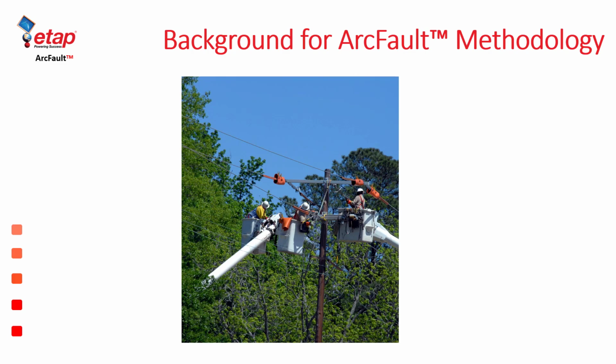Once the electrical workers cross these boundaries, they are exposed to a variety of potential arc faults. In overhead transmission systems, these arc faults may include series on-load arc faults, which occur as disconnecting equipment operates. They could be exposed most commonly to line-to-ground arc faults, and of course, less likely, but still possible, line-to-line arc faults, and perhaps even three-phase open-air arc faults, which will be, of course, considered the least likely possibility.